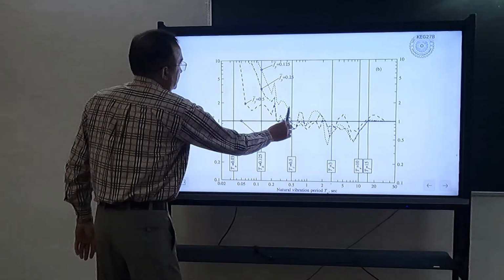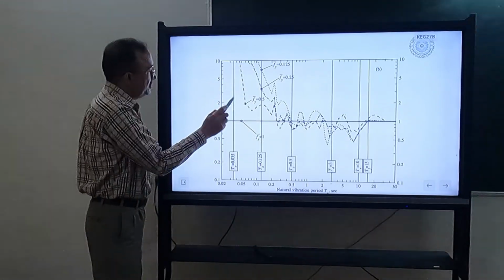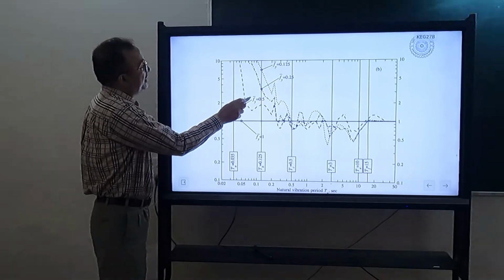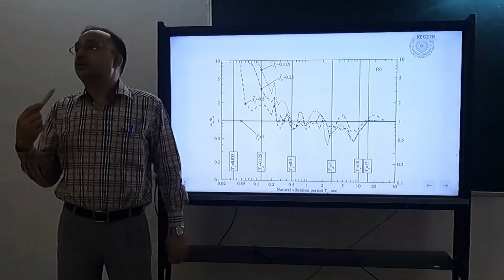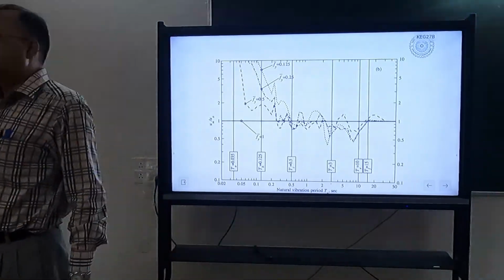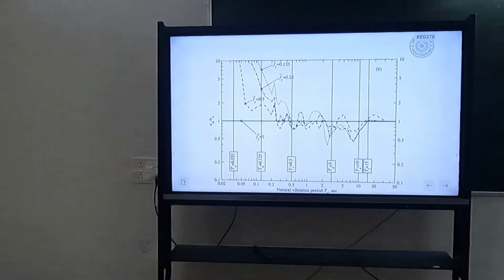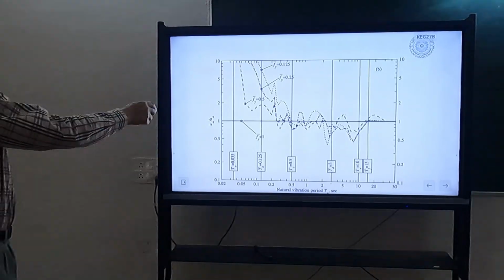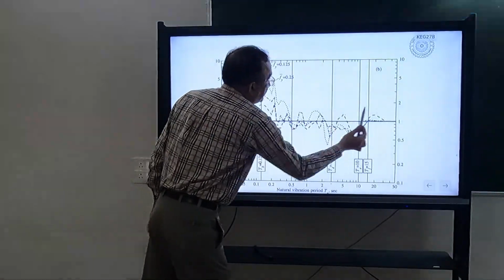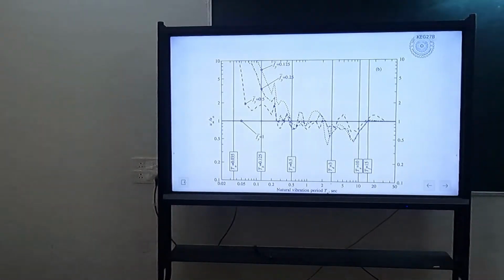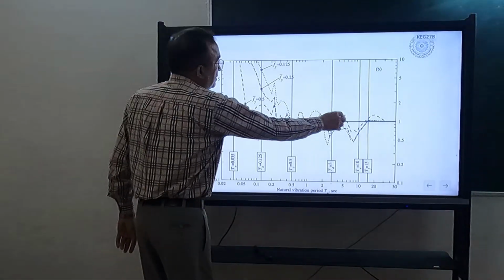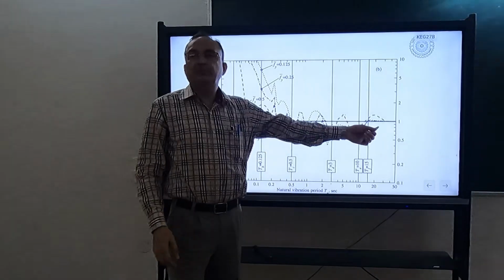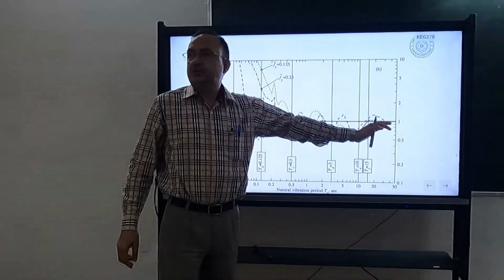Whereas here you see, here what is happening? As the Fy bar is decreasing or response reduction factor is increasing, you can see that the displacement goes on increasing. So displacement of the inelastic structure is more than that of the elastic structure, and the displacement increases with the level of inelasticity. So for larger inelasticity, there is larger displacement. Whereas here in the long period range, it is more or less constant. Same observation we have used in our first semester as principle of equal displacement and principle of equal energy. Okay, so if you do it for large number of earthquakes, then it will become smooth, and this will follow this line.